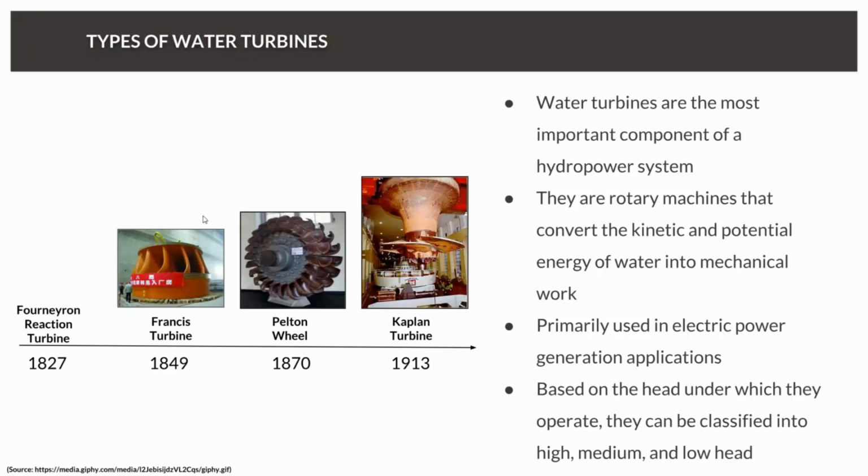After that, the Francis turbine was produced in 1849, and the interesting thing about that was there's been other things designed afterwards, but actually this is the design that stuck. It's like a combination of reaction and impulse forces. So it's using the blades like an aircraft in one way, and it's also using the impact force of the water to move the external outside blades too. So it's using the water in 2 different clever and combined ways.